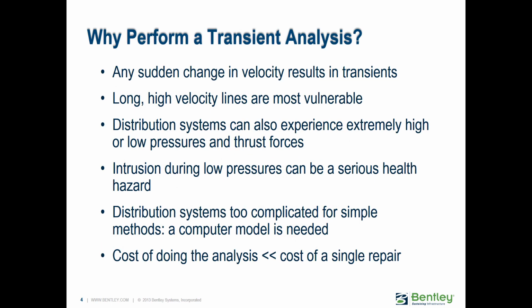All right, so why would you perform a transient analysis? Well, as I said, anytime you have a sudden change in velocity, you have a potential for a transient. And especially if you have a long, high velocity main, where if you have a transient, that's going to result in a relatively large change in velocity and momentum, which means likely a better chance that you're going to have a damaging surge.